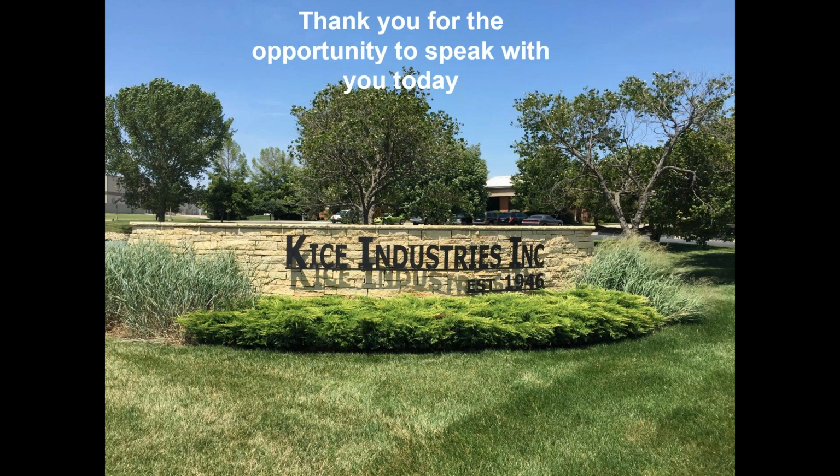There are a lot of filter bag makers out there and a lot of different technologies, and there are arguments for one versus another. But as your filter media increases, 12 ounce to 14 ounce to 16 ounce, you're going to have a more dense fabric, and again, depending on the dust, your pressure drop, your pressure differential across the baghouse may increase a bit faster.